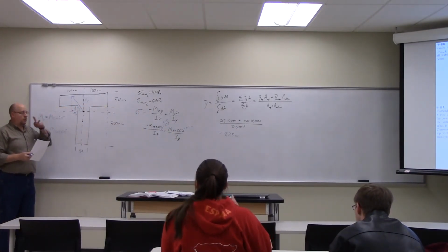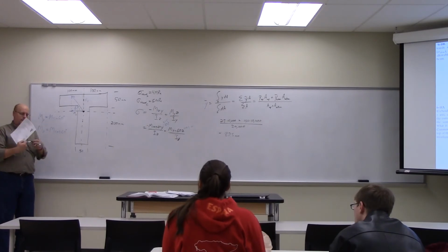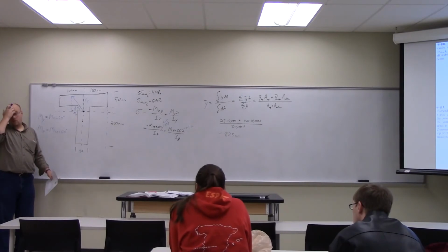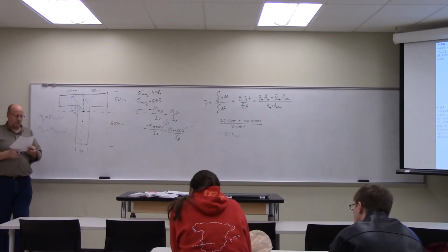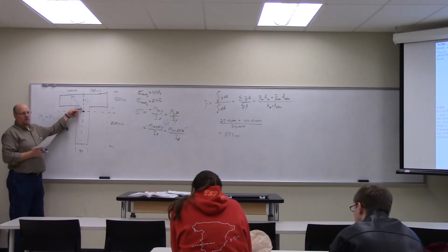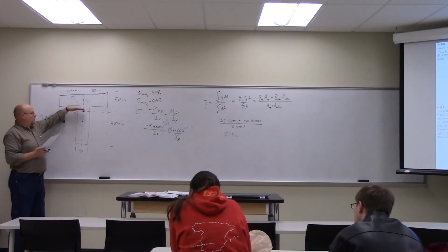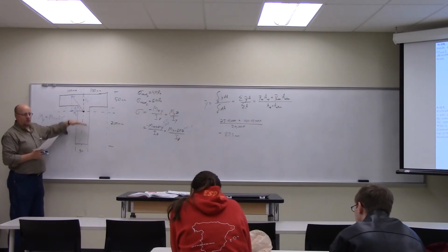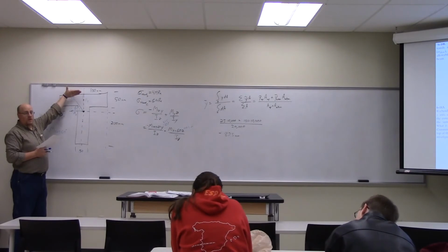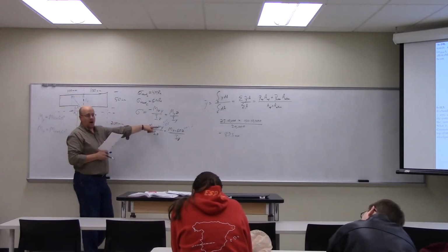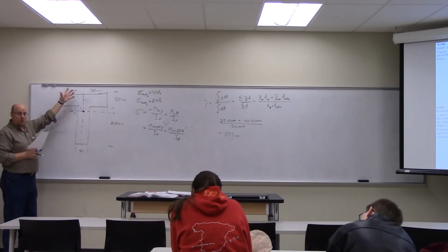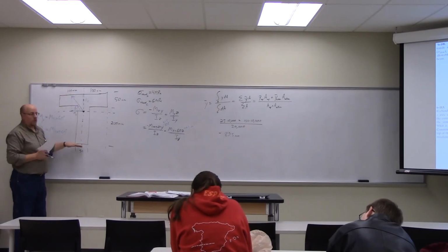At the bottom. Which one of those two are we going to use? I'm measuring from the bottom up, so this is 162.5. In other words, this distance here is 162.5 and this distance here is 87.5. My point is, we're using the maximum y value to find our maximum moment. So I found this one and this one. Which one am I going to use?